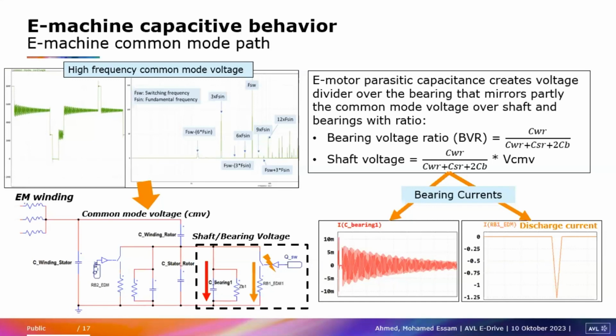At lower speeds, where the lubrication film thickness will be less, it will get to an ohmic behavior. When the voltage here is bigger than the breakdown voltage of the lubrication, it will actually discharge through the bearings with whatever current, depending on the resistance. This resistance also depends on the speed and so on.